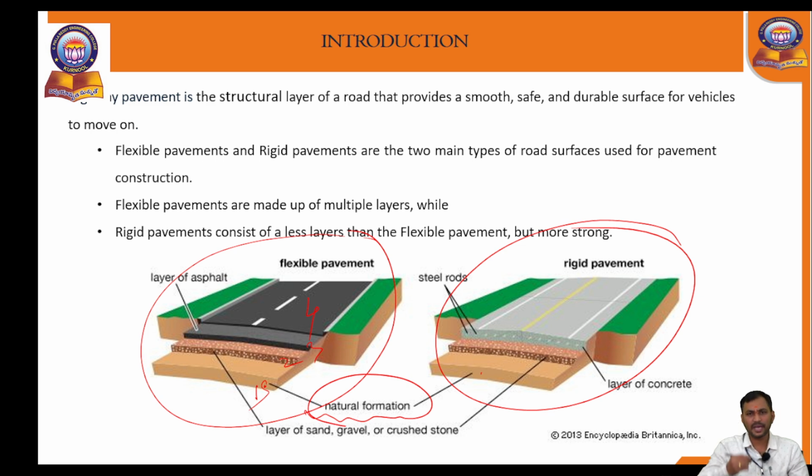Sir, why should we not construct the road on the ground surface? Because on the ground surface the available soil is topsoil, which is somewhat loose in nature. So that's why we dig or excavate the ground until it gets hard. For this type of road surface we can dig up to 120 to 150 mm thickness. Okay, we will discuss in the next slides.